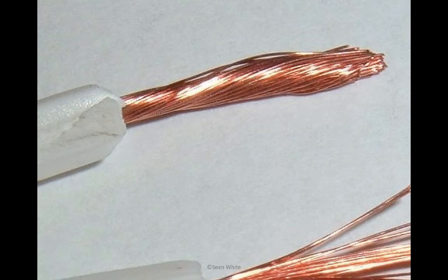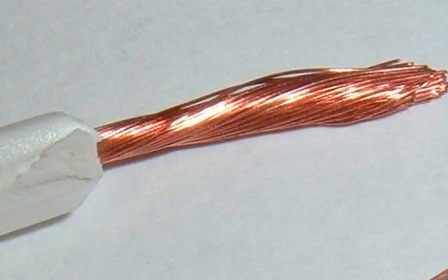There's a temperature rating of the insulation, and then there's a certain amount of metal, typically copper, stranded or could be solid if it's a smaller wire. Let's first talk about the conditions of use, which are conditions that decrease the ampacity of a conductor due to heat. That means that if we have a conductor that's got insulation around a piece of wire and we put that in a hot place, it's going to heat up more.